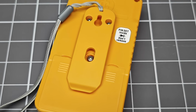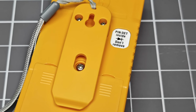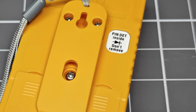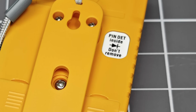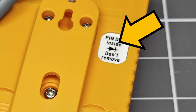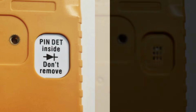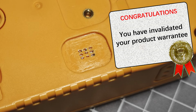The PIN diode detector is on the back of this instrument, and is apparently sensitive to alpha particles. In the form that it is shipped in, alpha particles will not be able to be detected by the instrument. The polycarbonate security label is just too impervious to alpha particles and needs to be removed. Once you have removed this label, according to the manual, you have invalidated the product warranty.